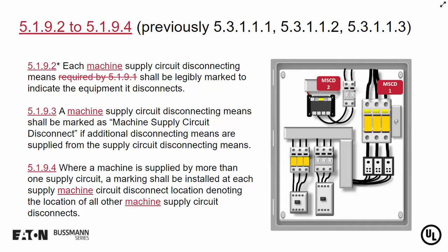So then you can isolate the equipment appropriately, whether you need to isolate all of it, de-energizing all the equipment being fed by these disconnects, or selectively.